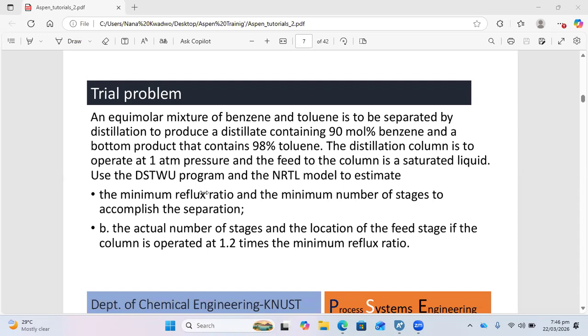Okay, so for azeotropes, yes, it's difficult to separate by distillation because as you heat it, part of it is becoming vapor and we still have some being liquid, but the compositions are not changing, right? So that's the main thing. The compositions are not changing, and so you can't do an effective separation. If you condense the vapor, you're getting back the same thing you started with. You've not done any effective separation at the end of the day. So that's the thing about azeotropes. You don't want to waste energy with such systems because you're not really going to do any separation.